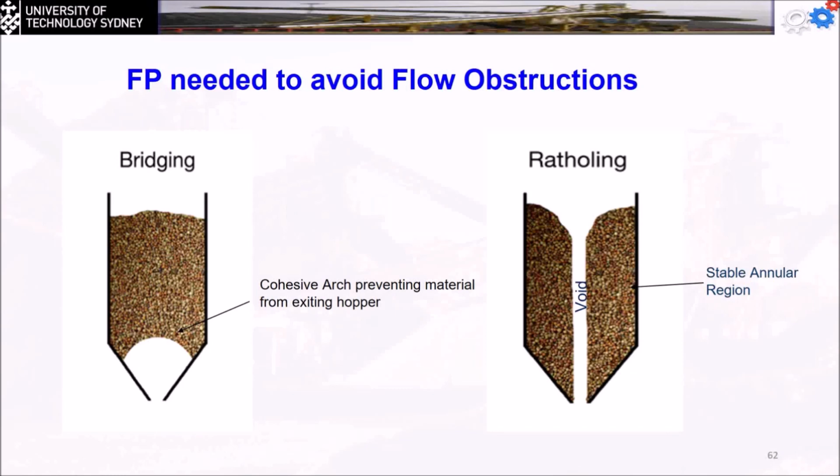But anyway, what happens in real life is that they're not going to inform the engineer about that. The workers are going to bring a hammer and start to knock on the silo, damaging the wall. It makes it work temporarily. But sometimes they put in vibrations, shaking everything so it flows down. You don't have to do it manually. Sometimes instead of vibration, they blow air in rings all over the silo to make the material flow down.